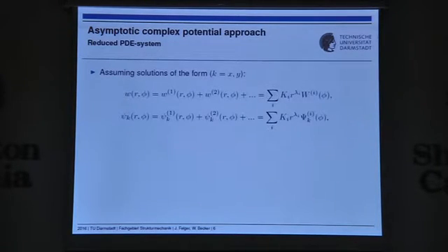So, based on the very general theory of elliptic boundary value problems near conical points, the solution in the vicinity of the notch tip can be expanded in this form here, where the first term here represents the leading order term approaching the notch tip. Here on the right-hand side, the singularity exponent lambda and associated stress intensity.